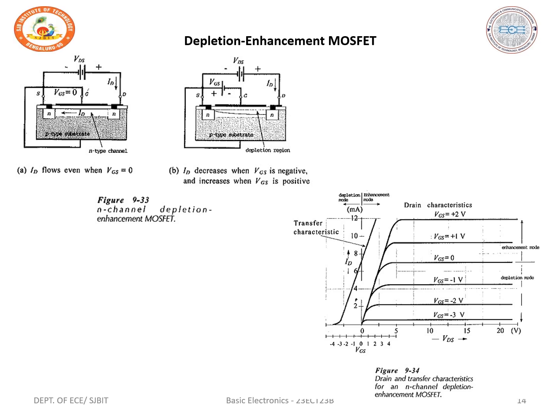The E-MOSFET does not conduct when there is no gate voltage, that is, VGS equals 0 volts. Therefore, the E-MOSFET is also known as a normally off transistor. In this there are also two types, P-channel enhancement mode and N-channel enhancement mode. Thank you.